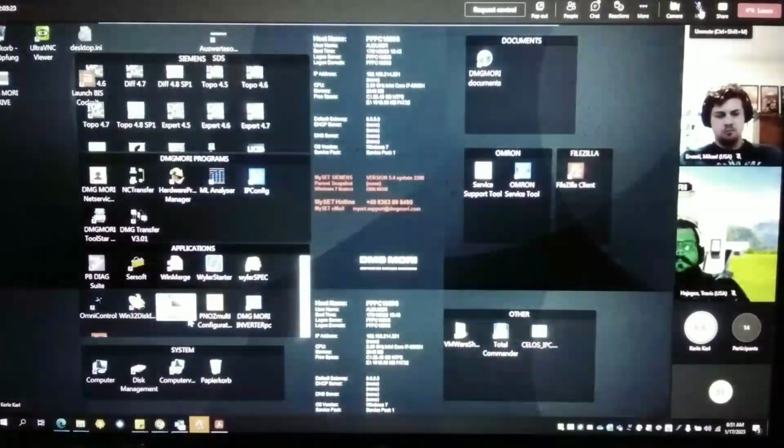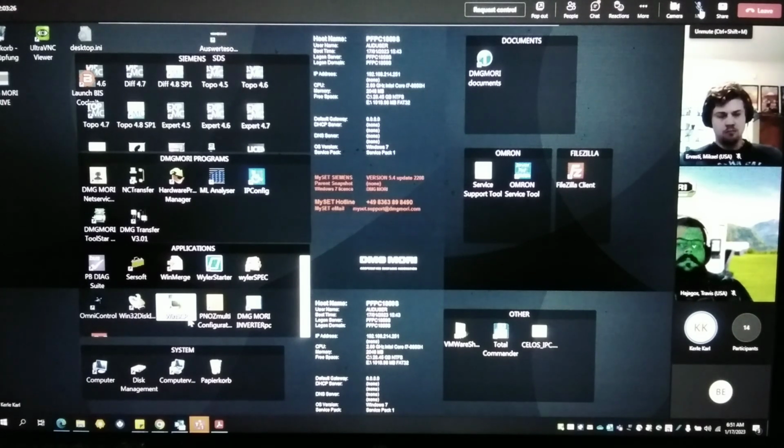Okay, that's for exchanging data, to have access to the CF card. This is the memory, the special hardware unit, where we save all the data within the NCU. Okay, and to get a connection to this CF card, we must use WinSCP. That's like a terminal program, also for translating the two different codes between Windows and Linux operating system, and to release a data exchange by a Windows-based laptop. Okay?